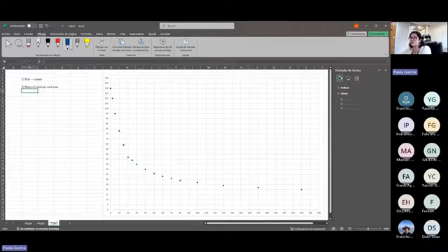So the mass of solids per unit area, we're going to call this M, and it is calculated as the initial concentration times the initial height. And if we analyze this in terms of dimensions, this would be kilograms of solids per cubic meter times meter.